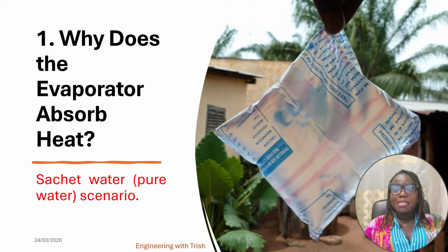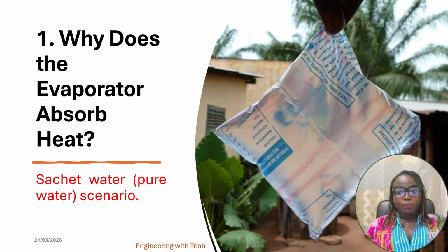After the heat is exchanged, the refrigerant is at a lower temperature. The pressure is still not so low, because the condenser is a heat exchanger. Then it goes into the expansion device, or the throttling valve.